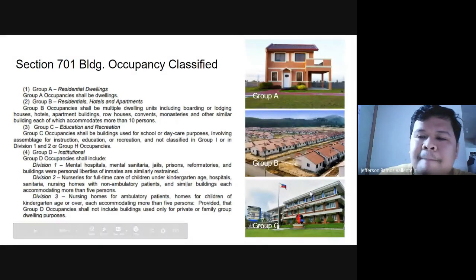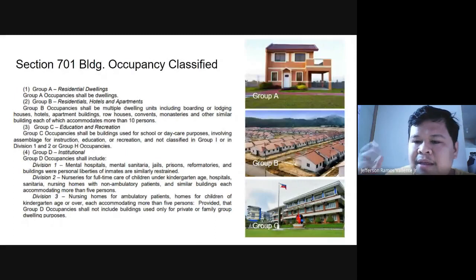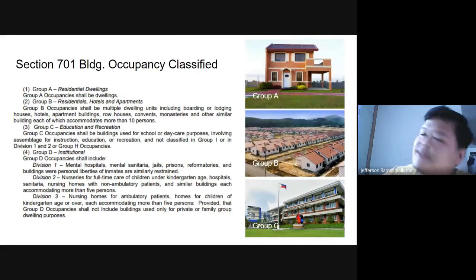Because with housing, you really maximize the freedom to see the other side. So the firewall is limited for group A. But for group B, because you use it as a common space, it can have 3 sides or even 2 sides as firewall. Or in a condo, only one side has windows. Or 2 sides if it is at the corner, but that is more expensive.